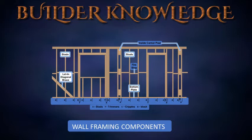Rough door and window openings. These openings must be framed into a wall wherever a door or window is planned. The rough opening for a door is framed with a header, trimmer studs, and, in some cases, top cripple studs. The rough opening for a typical window includes the same members as for a door, plus a rough window sill and bottom cripples. The tops of door and window openings in walls are usually in line with each other.